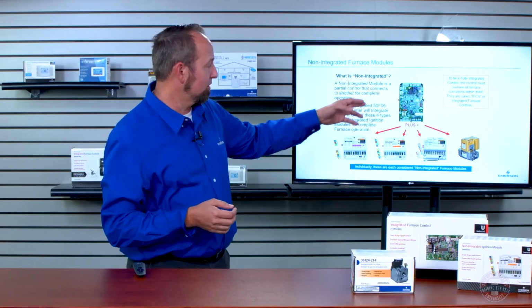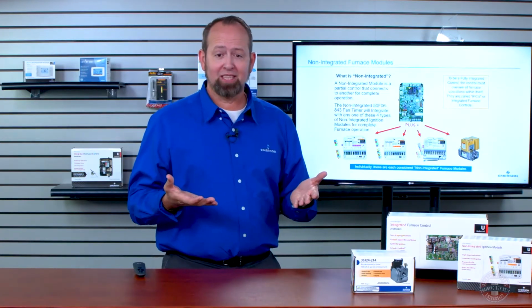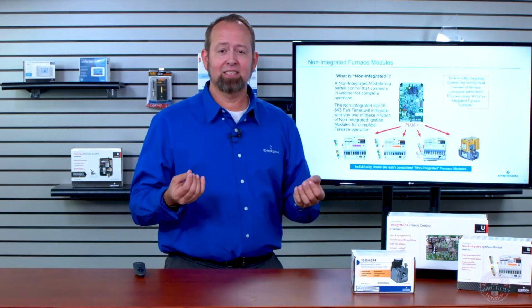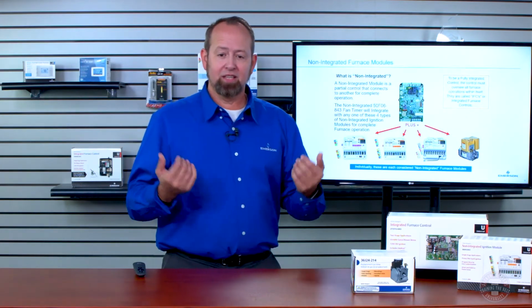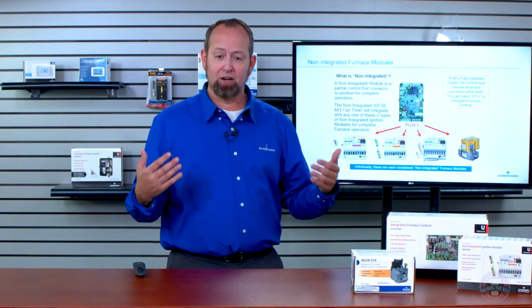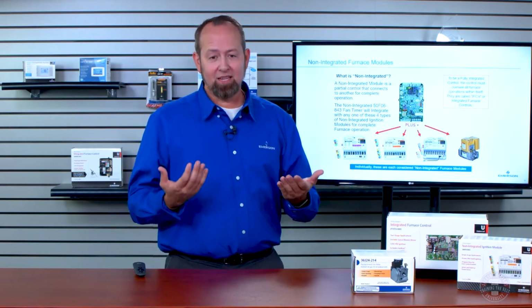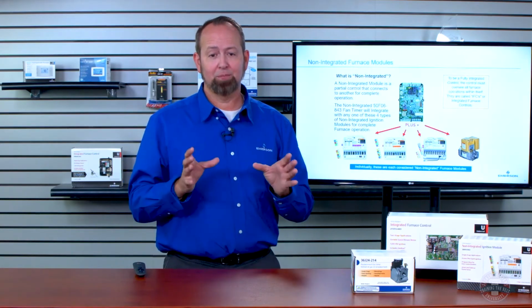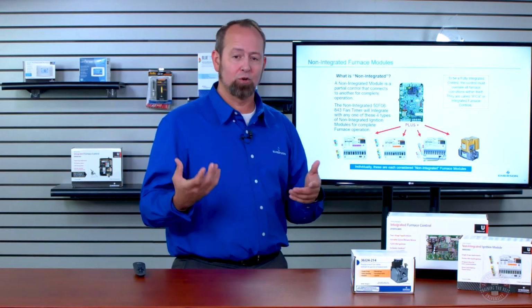The one here in the center of the top is a fan timer control, and that part would simply cover the operation, get the signal from the thermostat and send that signal onto an ignition type control, and the ignition control then would have all of the operation of the furnace firing and making sure that the burner is coming on. The fan timer module would simply operate and control the timing of when the blower motor would come on.